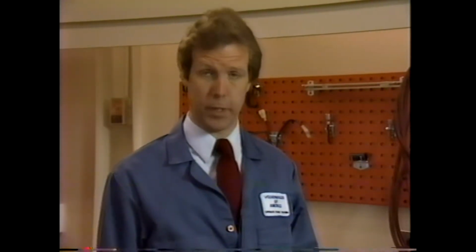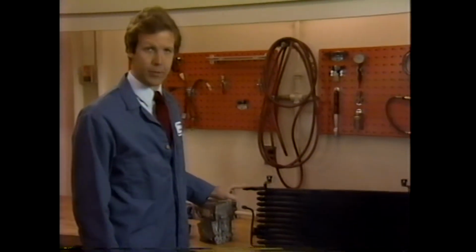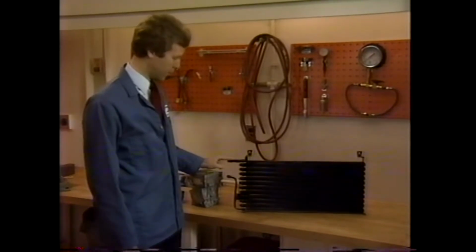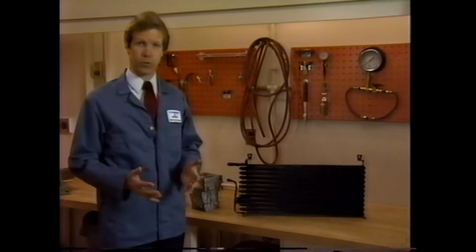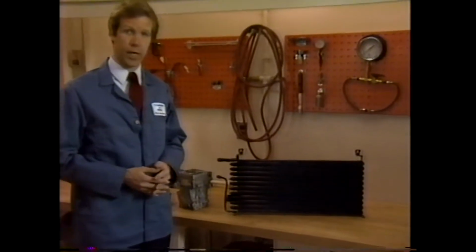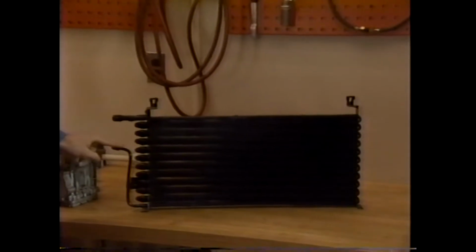The second change of state, this time from vapor to liquid, takes place in the condenser. The R12 enters the condenser as a high-temperature, high-pressure vapor. The condenser also works just like a radiator. The refrigerant loses large amounts of heat to cooler outside air. So the vapor has condensed to a liquid when it leaves the condenser.